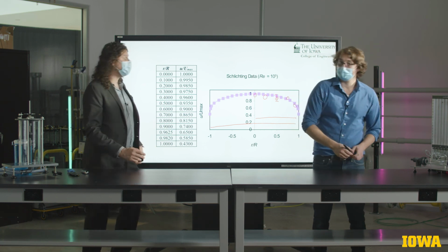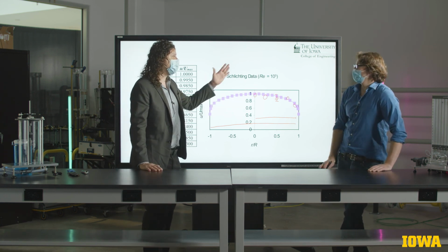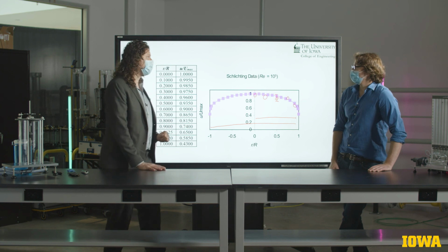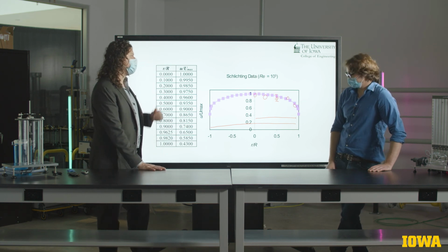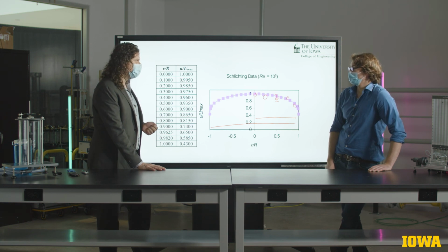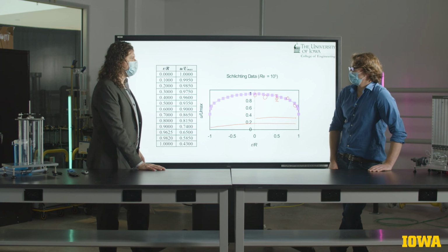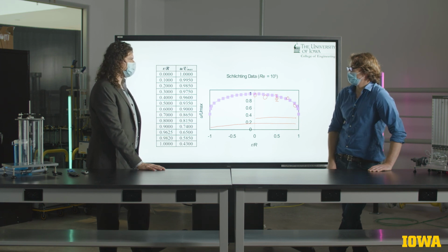So that uncertainty in our measurements of velocities is going to propagate into uncertainties on our estimation of flow, which then will translate into uncertainties on a Reynolds number, and then can be compared to our estimates of the friction factor.